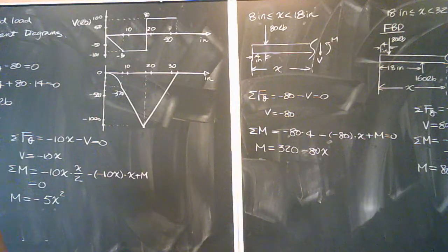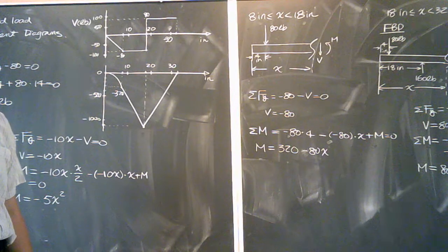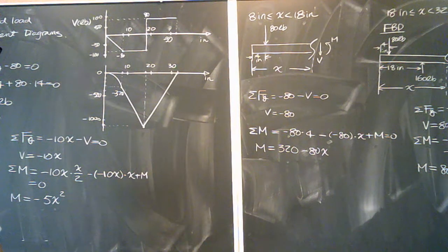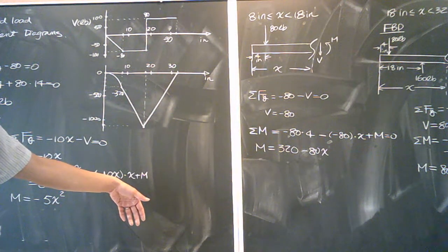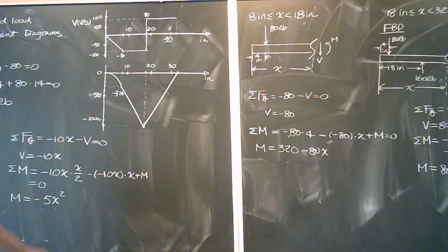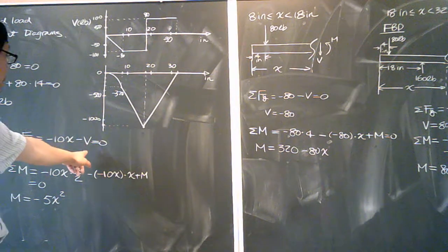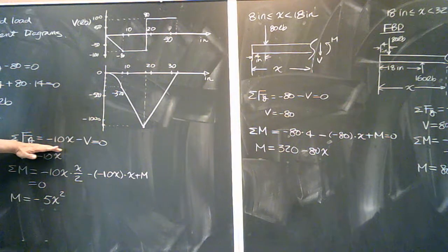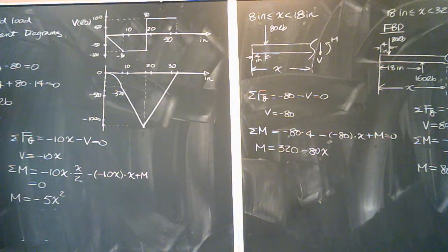I think this kind of problem is somewhat tedious, but I don't really feel it's not doable. You just need to be careful because each section, how many equations are you dealing with? 2. The only thing you need to be careful about is the moment arm and the V. In the force equation, be sure you include the term of shear force. If you fail to do that, you can never get the correct function in terms of x. That's number 1.